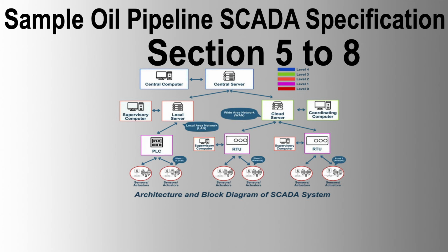7.2 Standard Software. Standard software is defined as previously installed and operated satisfactorily in similar control systems. Requires minimal tailoring with agreed parameters to suit specified requirements. Scalable for different site sizes. Standard documentation available. Correction updating facilities available to all users. Latest version supported by the seller. Configuration function blocks and ladder logic conform to these definitions.